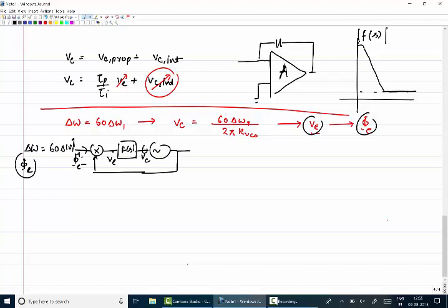How is this experiment different from the experiment which we were doing before by giving small values, right? Small values also we were actually specifying the exact value and just allowing a very small disturbance to take care of in the feedback. Okay, so this way also you can directly check for the holding range of the PLL.